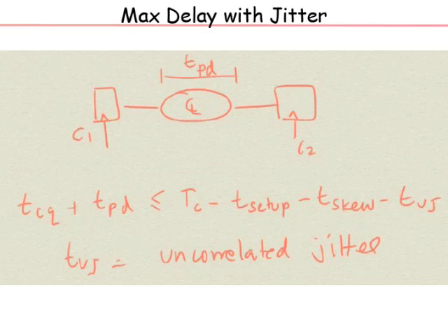Then the effect of jitter depends on where the data is coming from. For one clock, the data is coming in sync with the jittered clock, and for another clock, the data is coming in sync with the actual clock. See, say C1 launches the data and C2 captures. If C1 got delayed due to jitter, and C2 also got delayed by the same amount, then when C1 launches and C2 captures, both are shifted by the same amount. It's when they are uncorrelated, when C1 launches a little later and C2 comes a little earlier, that sometimes you have a problem.